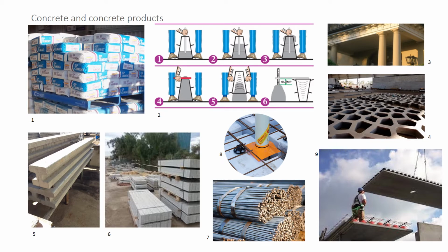Concrete is a composite material which consists of a binder, cement and water. Remember, cement is a powder; cement and water are commonly referred to as the paste, and then there is the aggregate. The paste will also usually contain some entrapped air. Aggregates are generally classified into two groups: fine aggregates, which consist of sand with particle sizes less than 5 mm, and coarse aggregates, generally crushed rock of varying sizes but greater than 5 mm.